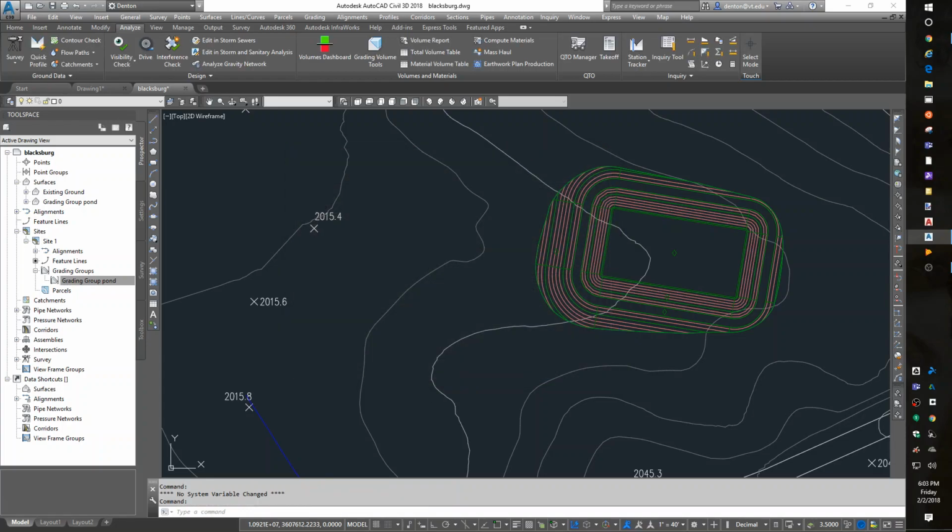What this is telling me is that I dug out a bunch of dirt for the center, but that was only about 1,000 yards of dirt. But I made this huge bank over here on the left of fill dirt so that my pond would be flat. And that is way more dirt, so I need to buy dirt. Well, I don't want to buy dirt. So the thing I'm going to do is move my pond down. I'm going to make it lower.